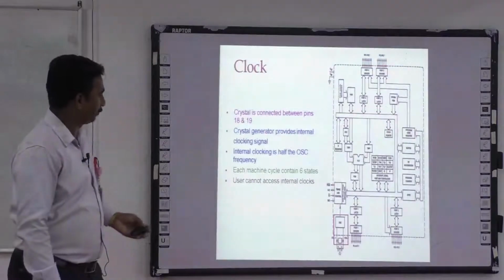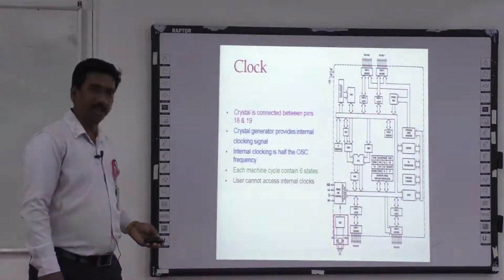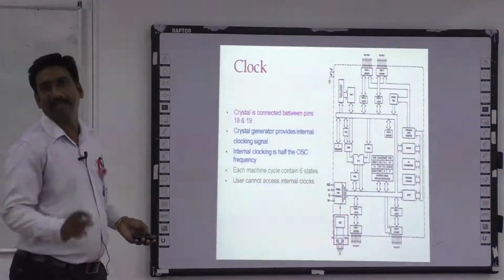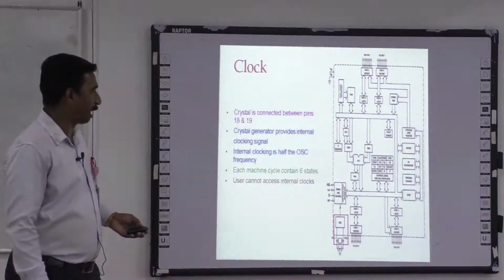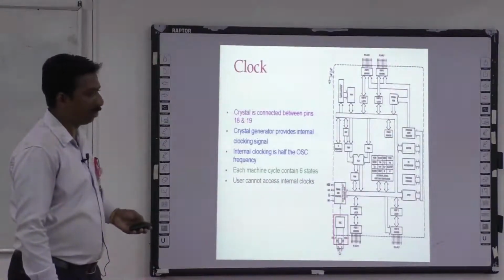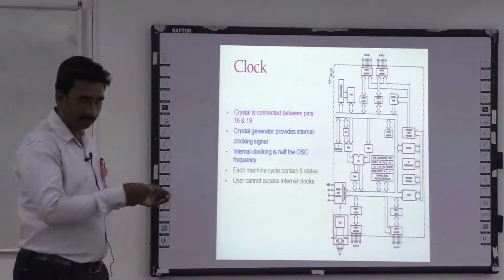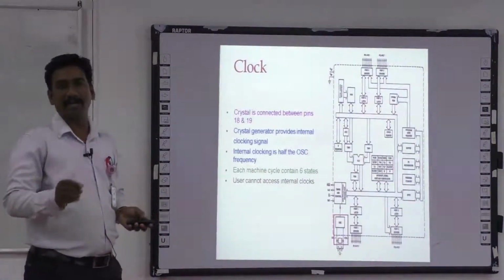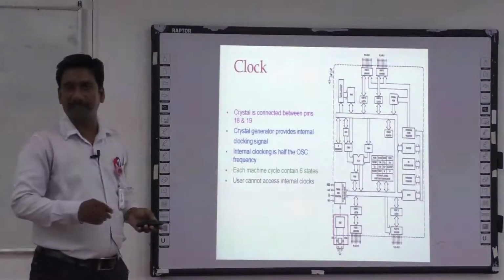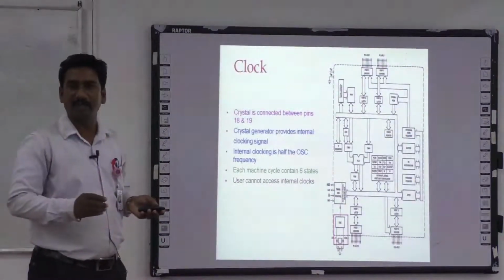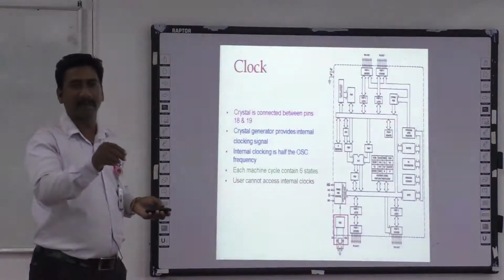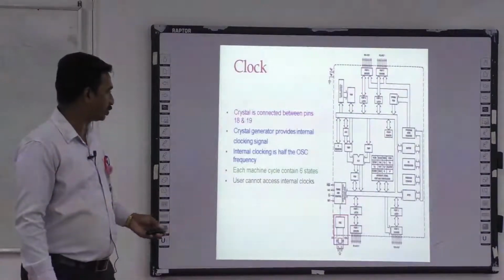And next one is clock, and that is generated by crystal with the capacitors. In hardware, crystal is there, and we have to connect the capacitors, and that will produce the heartbeat to the timing and control circuits, and that will make the rhythm of the particular speed. And there are crystals available in the market of 12 MHz, 20 MHz and 48 MHz. So the hobbyist or the person who develops the instrument will buy the crystal, and they will connect it with the capacitors and generate the timing and control circuits.